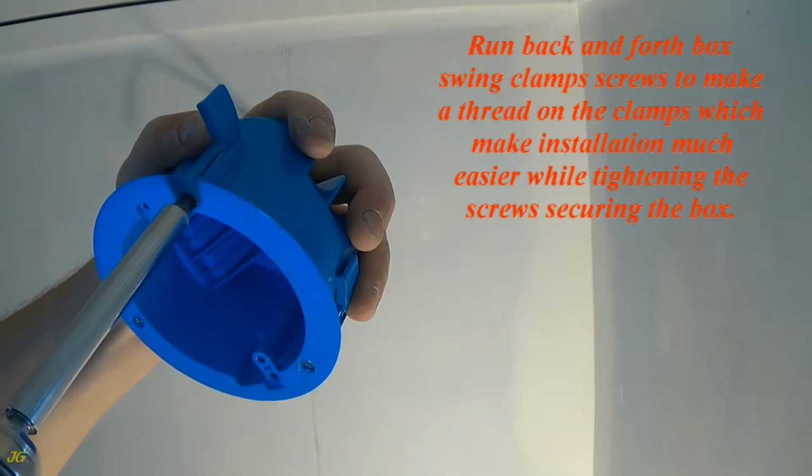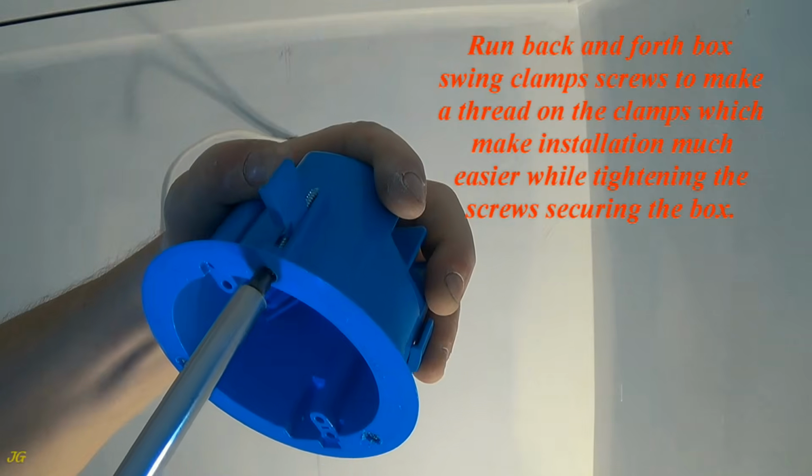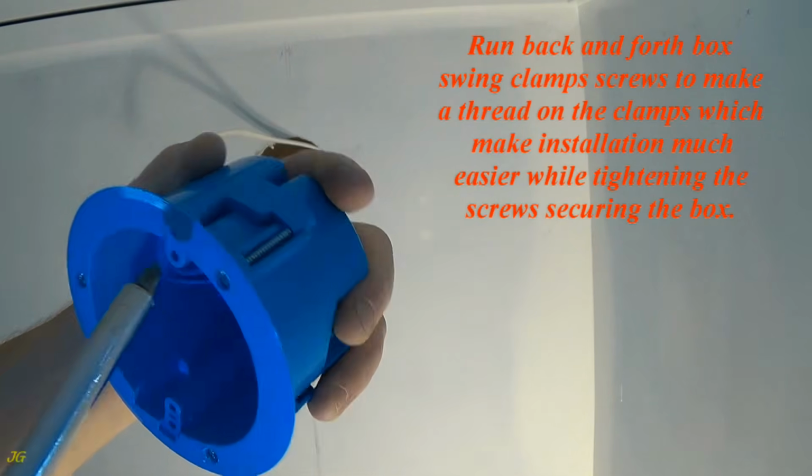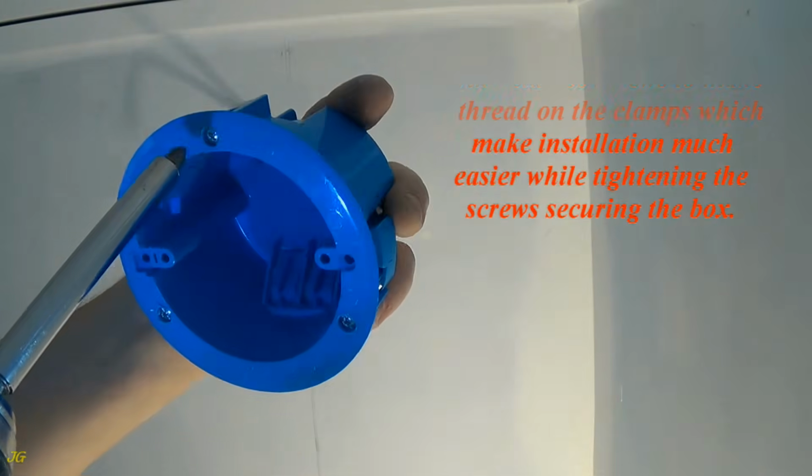Run the box swing clamp screws back and forth to make a thread on the clamps, which makes installation much easier while tightening the screws securing the box.